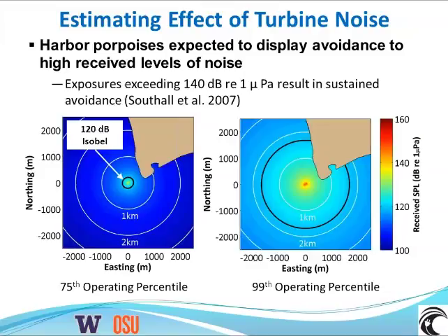Certainly, when the turbines are not rotating, one would expect the devices to produce very little noise, and at full power output, more noise. So if we adopt a very simple model for turbine noise, relating the noise generated by the turbine to the amount of power that it's extracting from the flow, we can work up a probability distribution of how much noise these devices might make. So again, this is a specific case of two 6-meter open hydro turbines deployed off of Admiralty Head in Puget Sound.